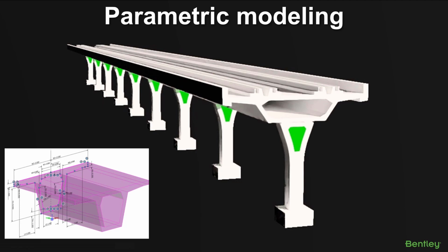For example, where you had to draw a myriad of individual separate models just to represent simple dimensional variations of the same component, now you only need to create one model and you can save all the different dimensional variations as saved sets of values. This makes your content library smaller on disk, so it helps you to reduce file size, but also makes them less complex, so you don't have to browse through hundreds of models, but only maybe through a handful. Parametric models and components can also be driven by item types, making your content libraries more intelligent and integrated.